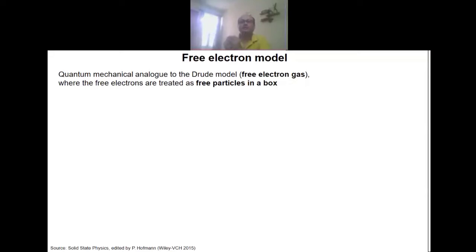But if you have an extra atom present at the center of this kind of box, then it's called the body centered cubic. But if you have the extra atom at the faces of this cubic unit cell, then it is called the face centered cubic, FCC structure.